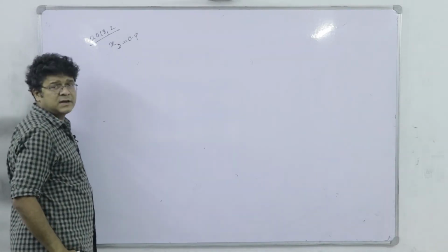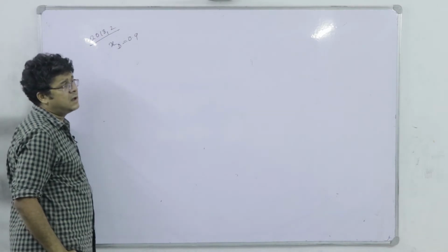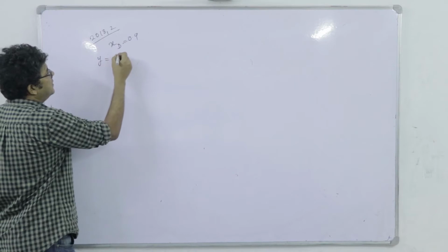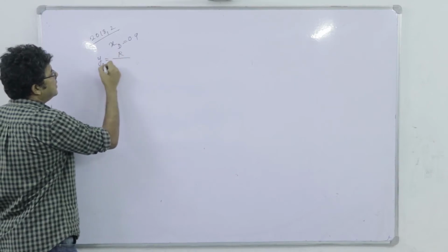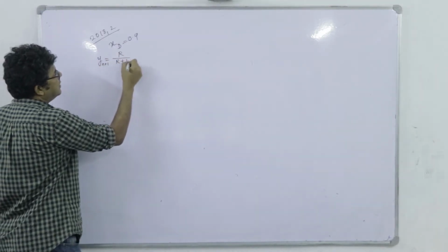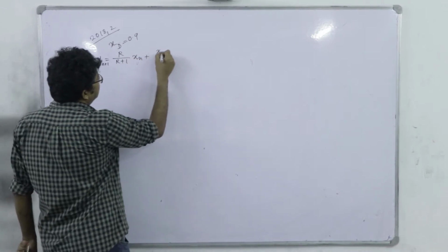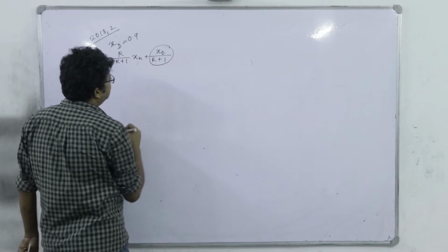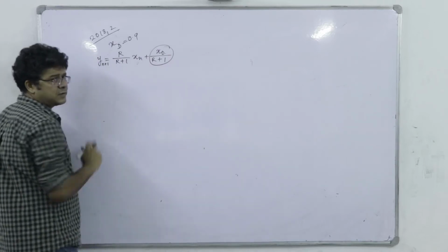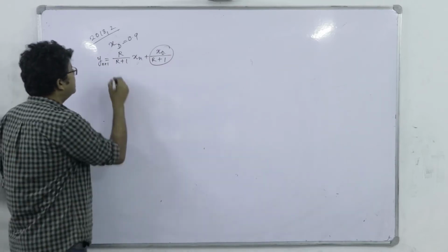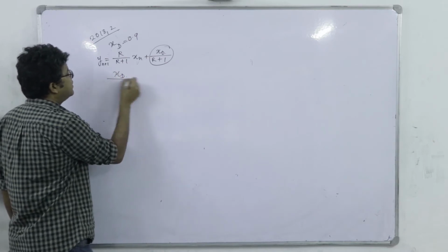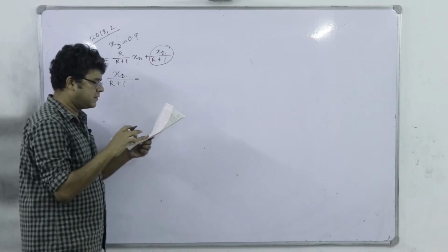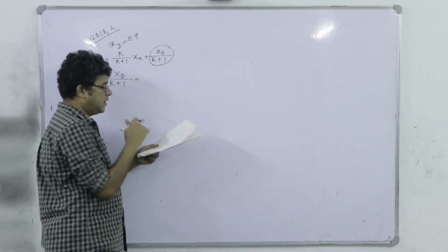This operating line is y(n+1) equal to R by R plus 1 times xn plus xD divided by R plus 1. This is the equation of the operating line for the rectification section, so the intercept xD divided by R plus 1 is 0.3.